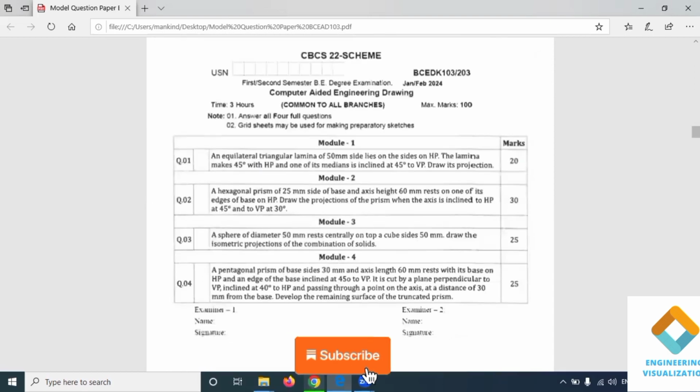You can see: an equilateral triangular lamina of sides 50 lies with one of its sides on HP. The lamina makes 45 degrees to HP and one of its medians is inclined at 45 degrees to VP. Here the angle of inclination is given with respect to the median. That means it is a beta angle problem. In this problem they have considered 50, but I will not consider 50. For showing purposes I will take 25 and then construct. So, beta angle problem. I'll show it in the SolidWorks software.